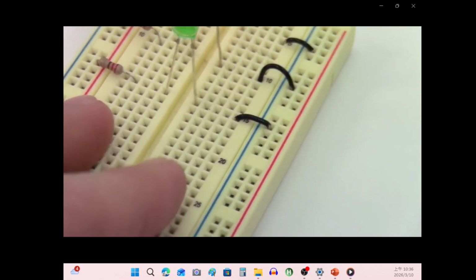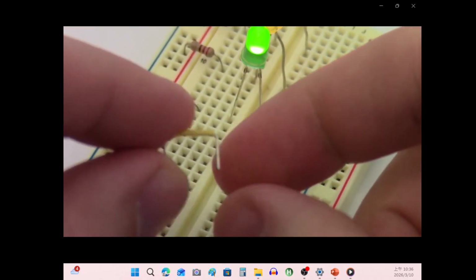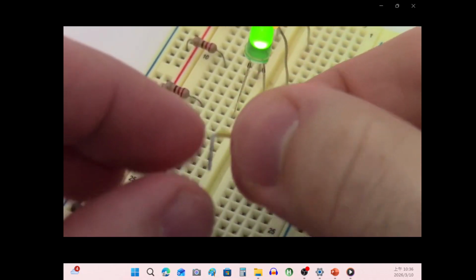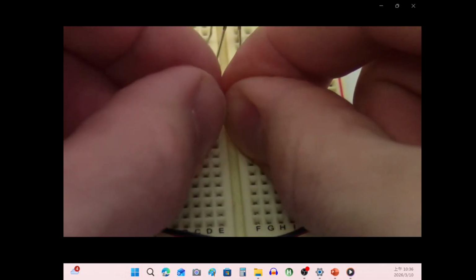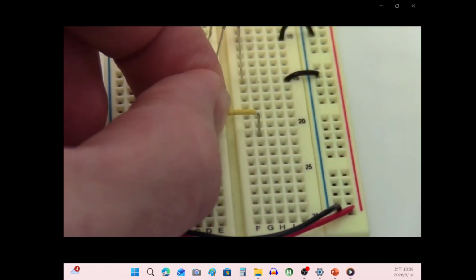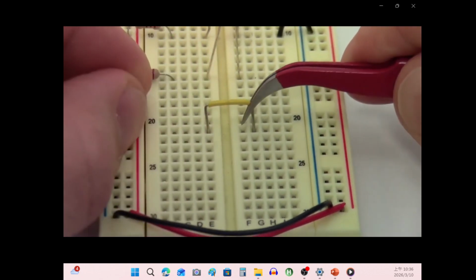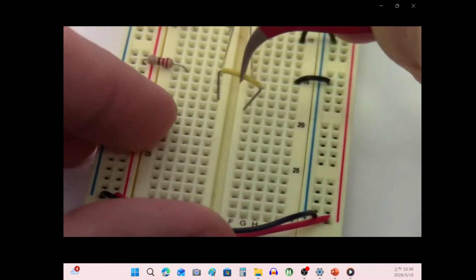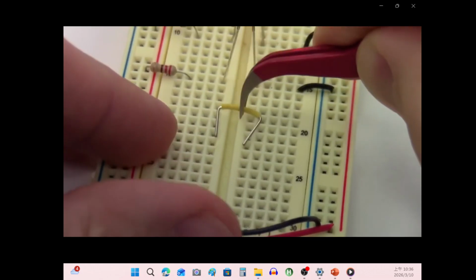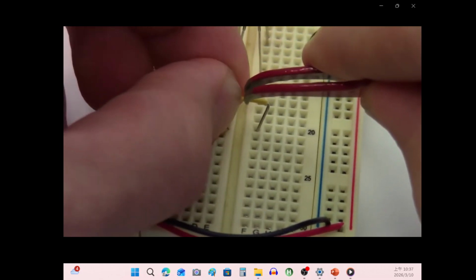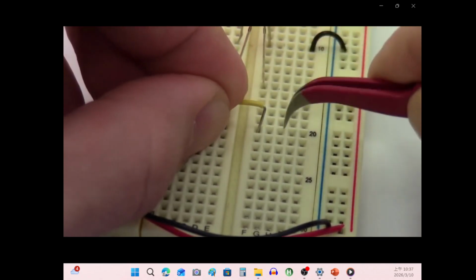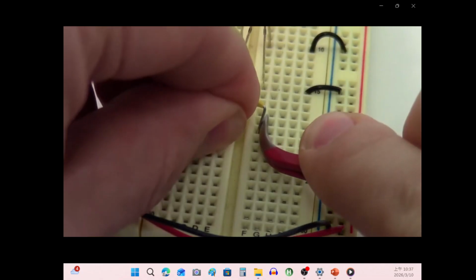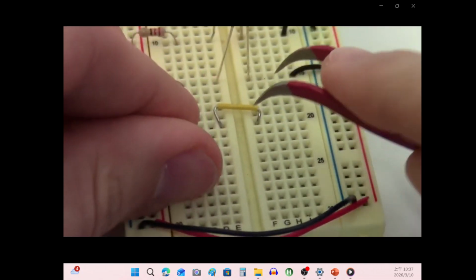So again, that is especially true if you are using these tiny pre-cut wires and the students are trying to force them to a certain distance. Say if I wanted to use this yellow one to just barely bridge that gap, and you see it's a little too long to do that. So what students will do is bend these inward and try to force it in like this, and then you won't get the full length of contact. They'll wind up kinking these and pressing the plastic down flat, but not necessarily actually getting the metal in all the way.